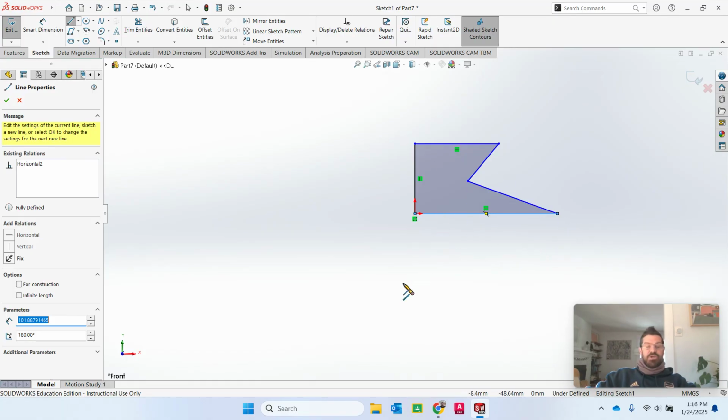Let's talk about some geometric constraints that I'm putting on here, though. It assumes that this line is going to be vertical, this line is going to be horizontal, this line is going to be horizontal, and it thinks that this line and this line are both going to be coincident with the origin, meaning they're going to stay locked in on the origin. Those corners are going to be locked in just like we had in AutoCAD. We were able to lock certain things together. It's assuming that those are locked onto the origin.